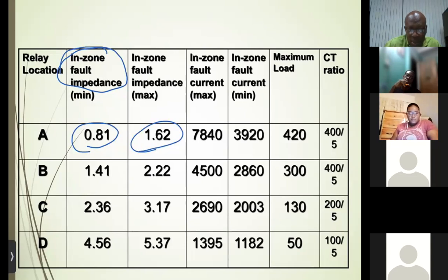That's how we get the 0.81. With the 1.62, that's with one transformer in, so it would now be 11 squared over 75. But we don't really need to work that out because we know this is at 150. So at 75, it must double. So we get 1.62.